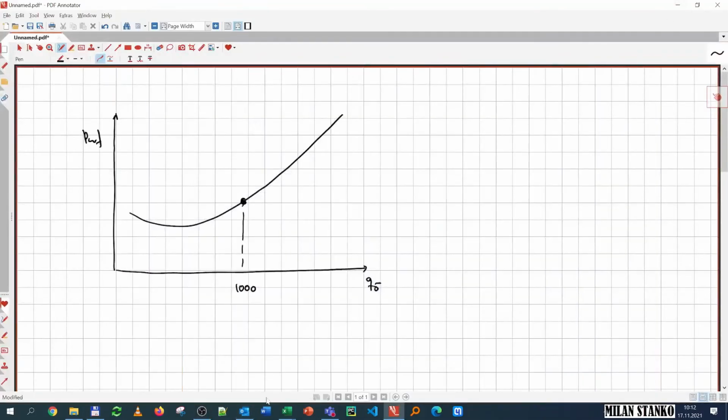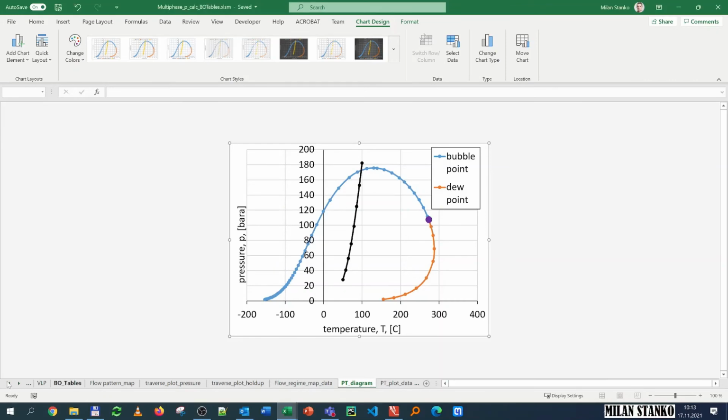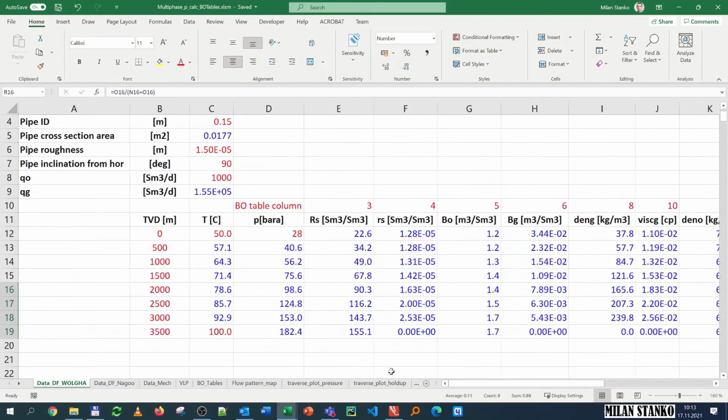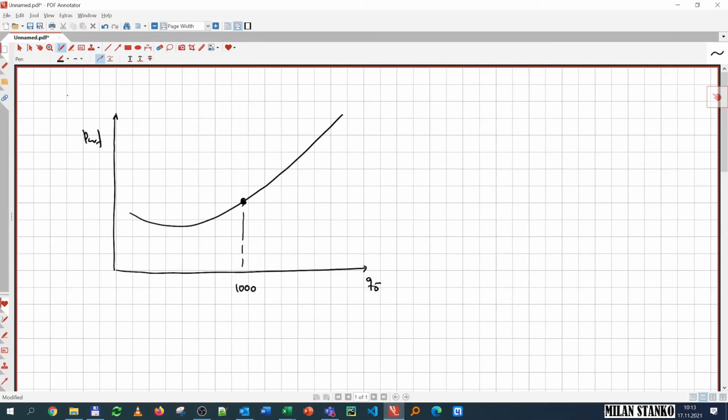So now our next step, now that we have this working sheet that we have made our calculations of flowing bottom hole pressure. What we want to make is, remember that we need this curve, that is the curve of required pressure at the bottom of the tubing, and this is made for a constant wellhead pressure. Okay, so this is for wellhead pressure equal constant. Okay, so we need this curve for making our flow equilibrium calculations. And so far, we have just one point.